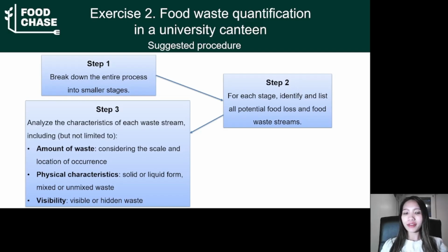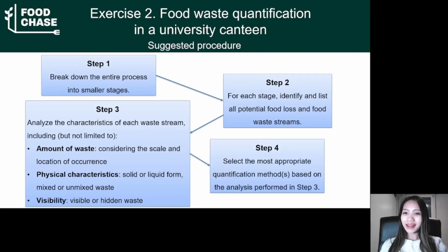Physical characteristic. You must determine whether the waste is solid or liquid. Is it mixed or unmixed? And finally, the visibility of the waste. Is the waste visible or hidden? Can you measure it or you can only calculate it from some other information? The last step is the selection of the most appropriate quantification method, based on the analysis that you have performed in the third step.